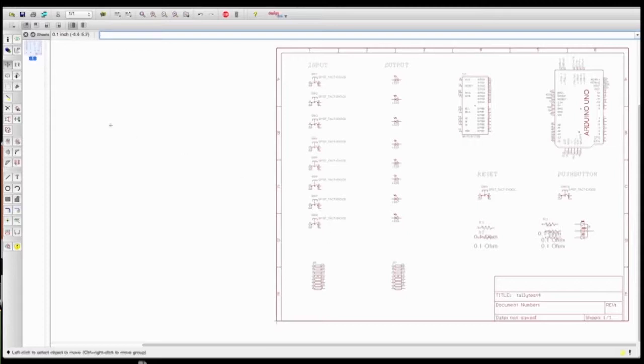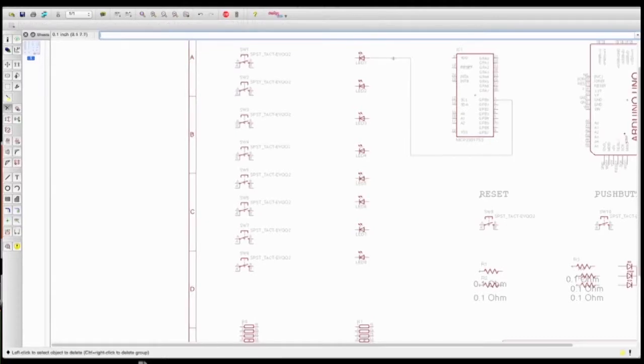So I could very easily do this, I'm going to undo it then. Let me come up here and we're going to say that this is LED 1. So I could run a wire just like this, and it'd be similar to the first thing. Now the one thing I mentioned before about layers, see how it's gray? It should be green. So that tells me I did it wrong.